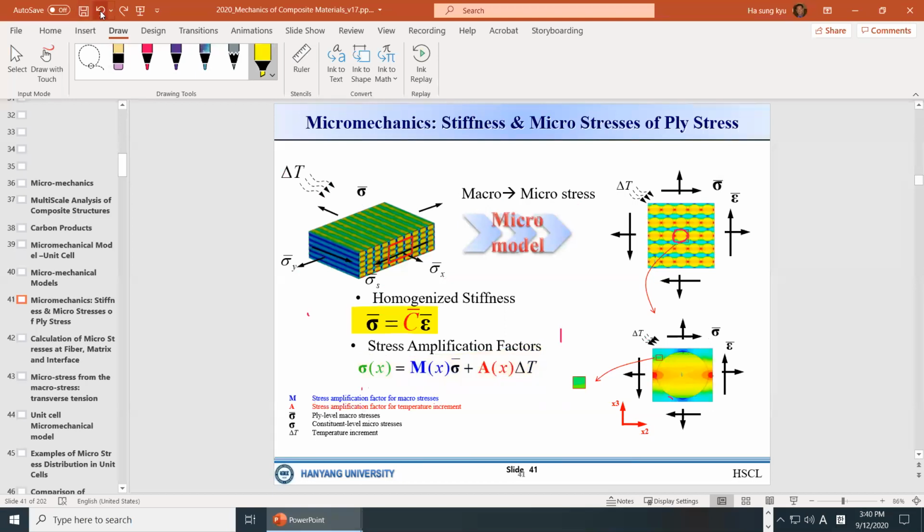More specifically, we calculate the C, we calculate this M, and if needed, we calculate the A. Of course, from this C, we get the S bar, and we get all the epsilon. I mean, Young's modulus EX, EY, and Poisson's ratio, and so on.